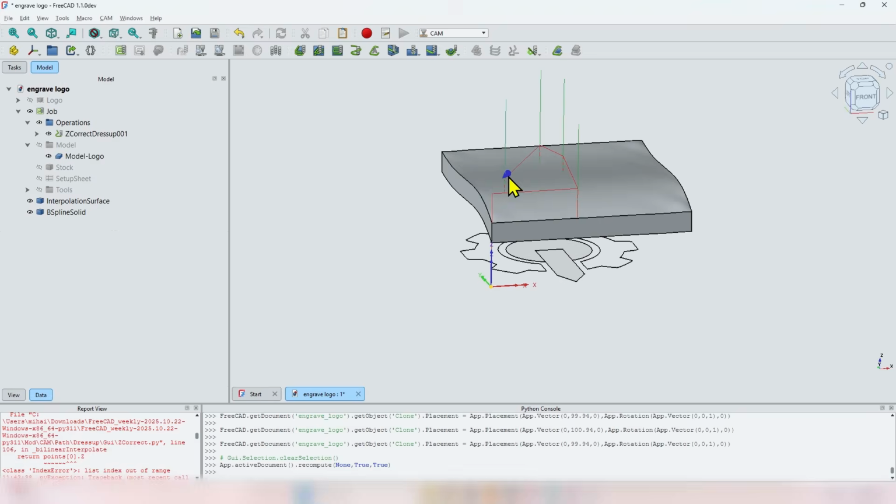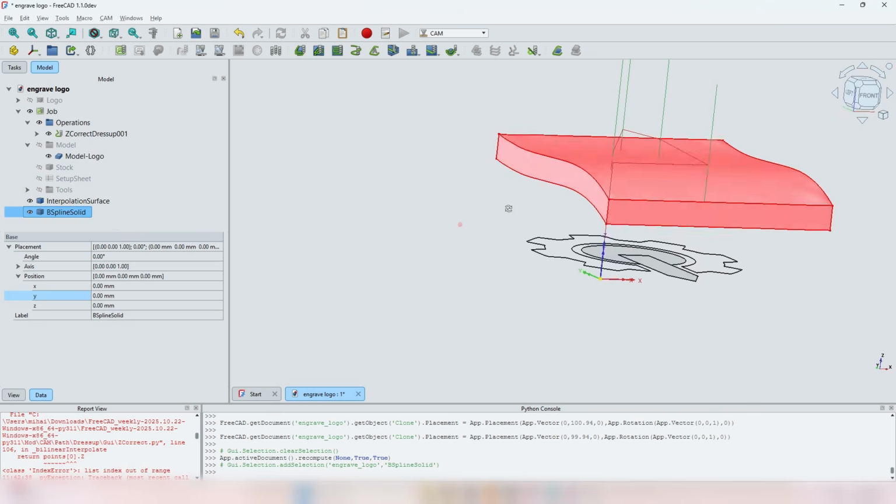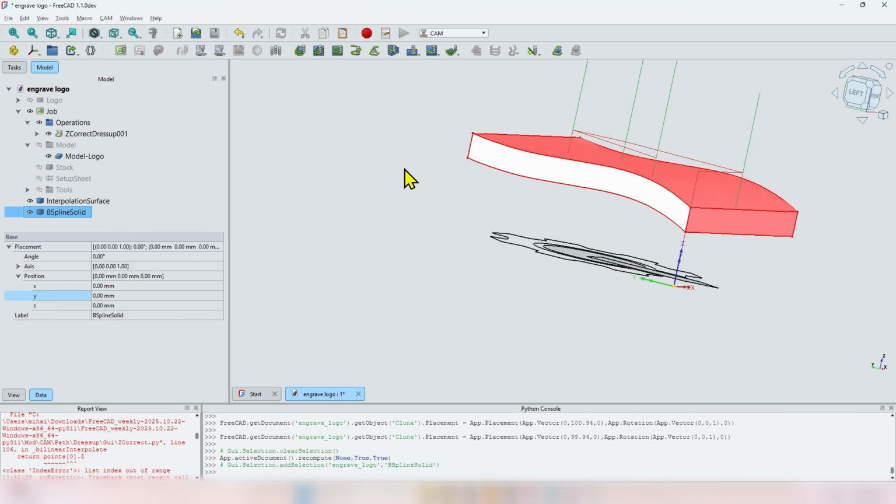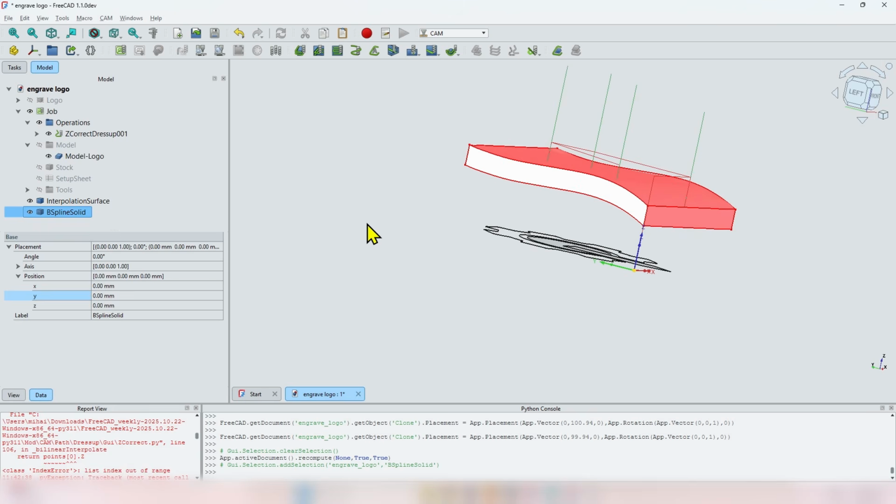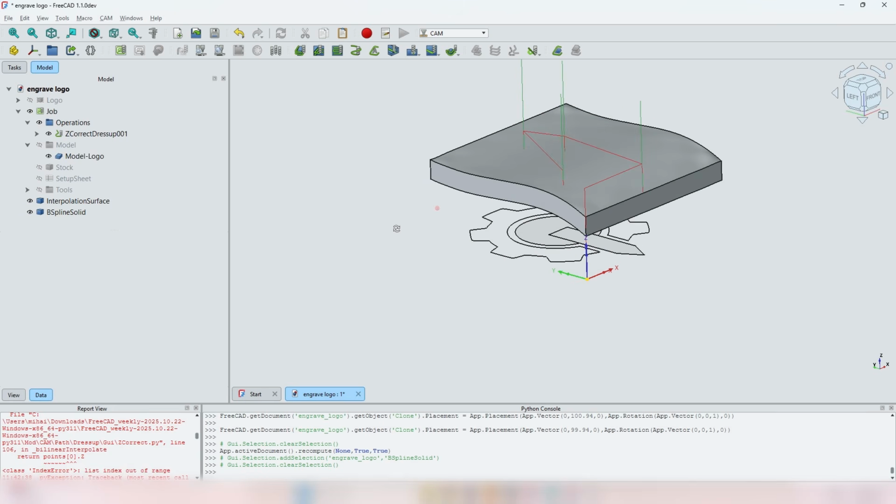Using the macro to generate the solid of surface will help you diagnose this problem. Of course, you can use this solid, intersect it with a cube, for example, and you will have a perfect replica of the material on the CNC table. You can manipulate it however you want it from now on in the part workbench. Now let's go to the machine and run the program, see what happens.